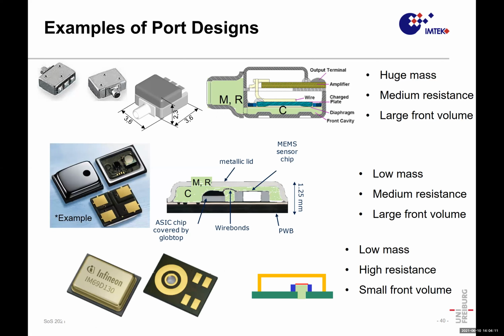And the most advanced microphones invert the situation. They don't have a lid or a cap with a hole inside. They rather put the hole on the rear side of the microphone. So then the sound enters on the back side into this microphone, and the package itself is the bigger volume. So this is the back volume, and this tiny one is the front volume. The tiny front volume, whenever you have something resonant, shifts the resonance to higher frequencies. So these are the three situations for port designs.